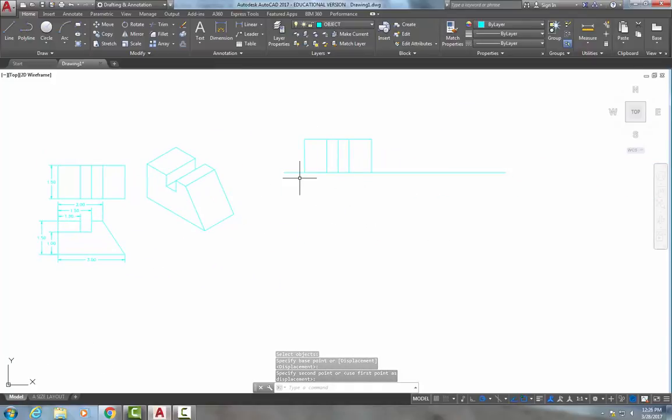Now, remembering back to when we set up 1 point perspective drawings, I talked about how we measure the width of this object, and the vertical line comes down approximately double that width. That's an approximate. We could use a little more, a little less, depending on the size of the object. This object is 3 inches wide, so I'm going to draw a line down that is 6 inches long.